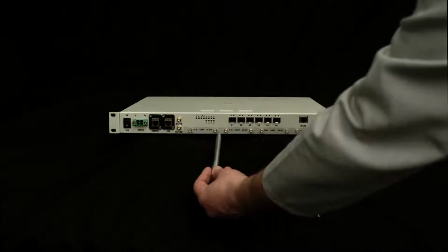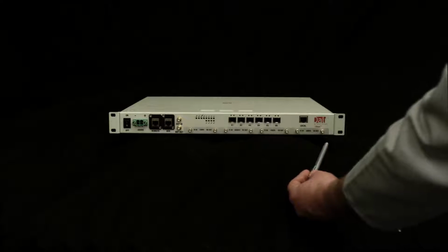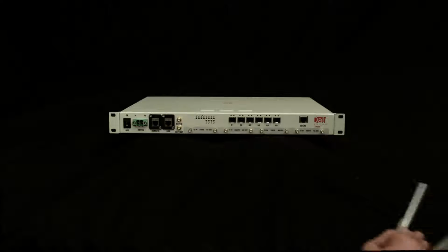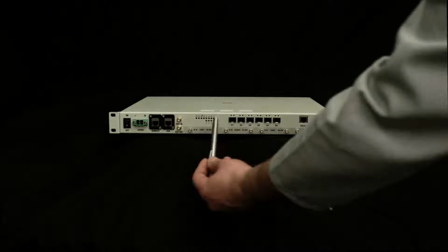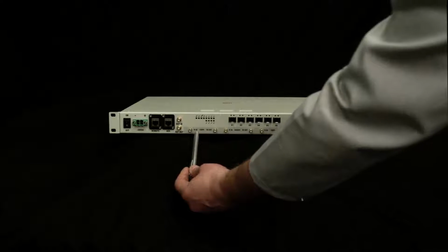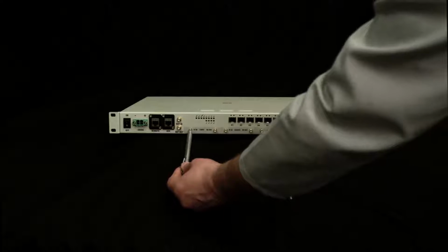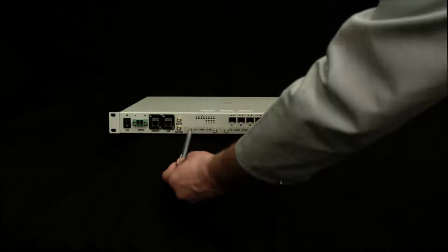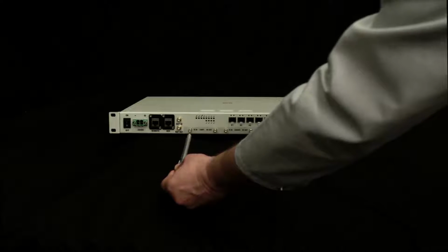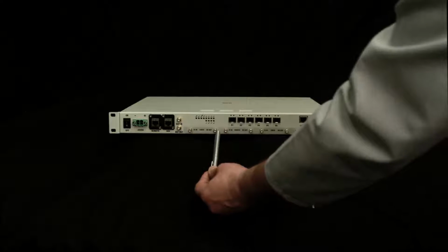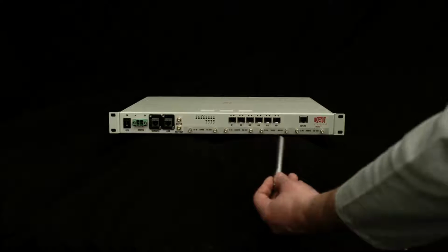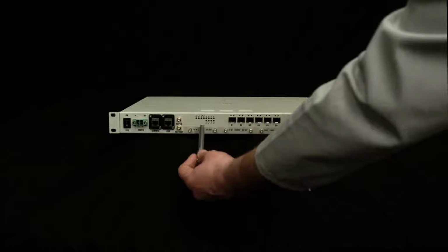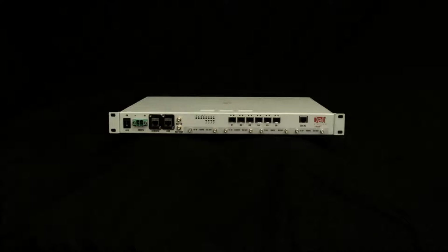So on the RF side, there are 8 simplex SMA connectors, and there are RF interfaces towards the base station. Simplex, meaning that each band has TX input and RX output. TX is downlink signal received from a base station. RX out is an uplink signal delivered to the base station. T-host is a quad band unit, hence 4 pairs of SMA connectors.